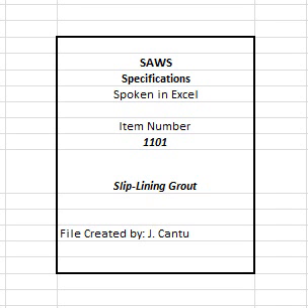5. The grout pressure recordings shall be identified as a minimum, with date, batch, and time of day grouting was performed and shall be submitted to the inspector at the end of the workday that grouting was performed. See procedure. 1. Place grout for a given pipeline segment between bulkheads. Place bulkheads at the ends of each pipeline segment to seal the annular space from sewer flow. Do not remove bulkheads until after grout has set.